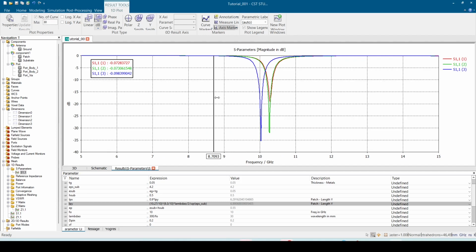So in the next videos, I will explain, if I have some antenna, what I should do to scale it to another frequency. So if you copy an antenna design from a paper, how you can scale it very fast to your own frequency, given the substrate effects and so on. And I will do further analysis on how to understand the results. So basically we'll be answering two questions: how I can be sure that this bandwidth which I get is maximum, or what bandwidth I should expect from the antenna, and how I can scale it to higher frequencies. And then if I scale it to higher frequencies, what is the bandwidth I should really get? So this will be the topic of the second tutorial.